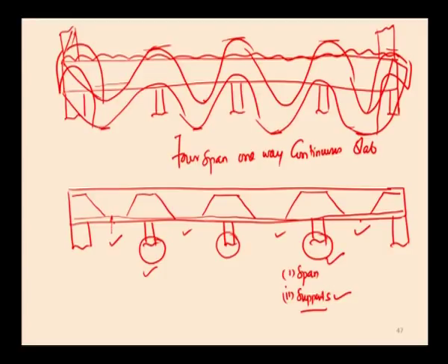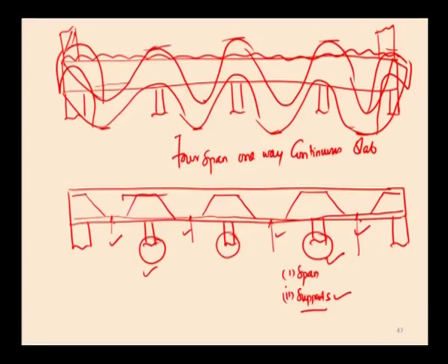Here we have provided 100% of reinforcement at the mid span. Alternate bars are cranked over the support, so over the support we have provided only 50% of the reinforcement. To make up the other 50%, a separate reinforcement has to be provided at all interior supports.